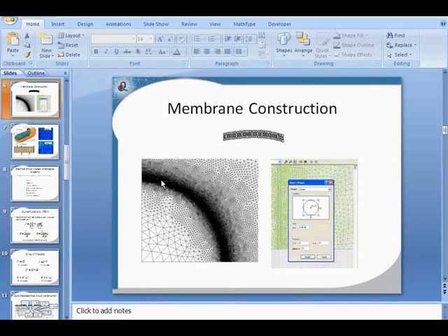Previously we looked at membrane construction using QuickField, and we could model the aspect ratio of cells and their membranes using a very high mesh gradient. We accomplished this by making spherical or cylindrical cells using the insert shape with circle type of elements with slightly different radii, and we can obtain a very high mesh gradient in these regions.